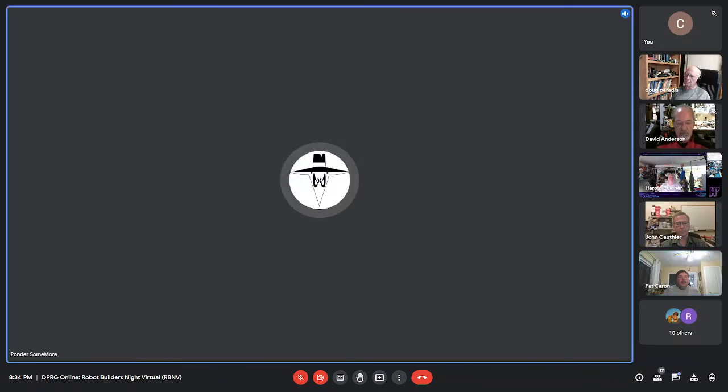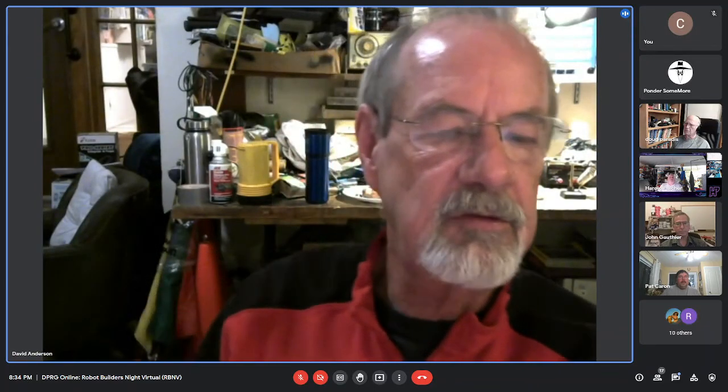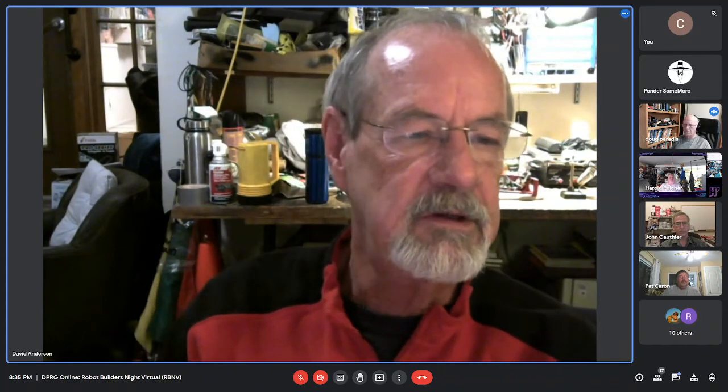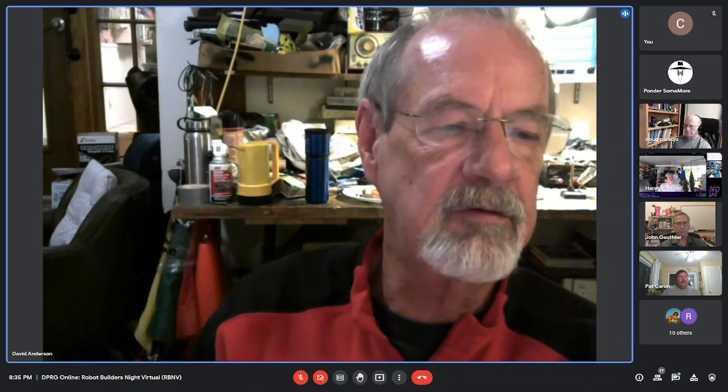Why are you integrating it yourself? Yeah, I'm not sure. That seems like a mistake. Now, when you say you're using the rate gyro, you're using the yaw. Those are two different things. Yaw is an actual heading that's returned by the IMU based on a bunch of things. But a rate gyro only tells you how much the gyro has rotated in the last sample time you're using. The gyro tells you the rate, not the heading. So you have to integrate it yourself in order to know the heading.